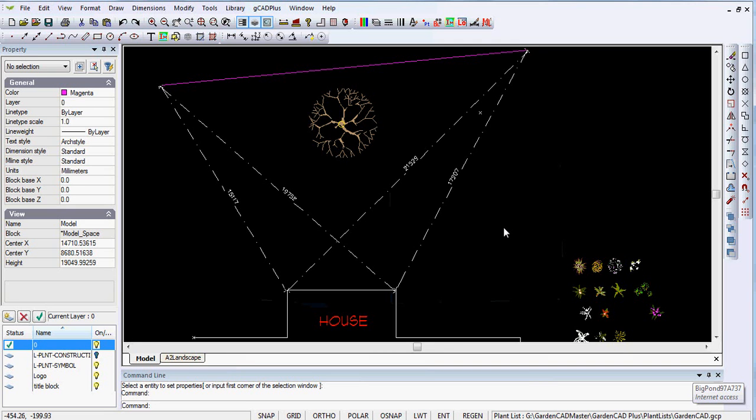The back boundary of a site can be located quite accurately, provided you have the house footprint down and you've been on site and measured distances from a convenient point. You want two distances from, say, the house footprint across to one corner and another two distances on the right-hand side in this example. You've created a couple of triangles. With those triangles, we can swing a couple of circles where they intersect will define this point of the boundary, and another two circles to define that point.